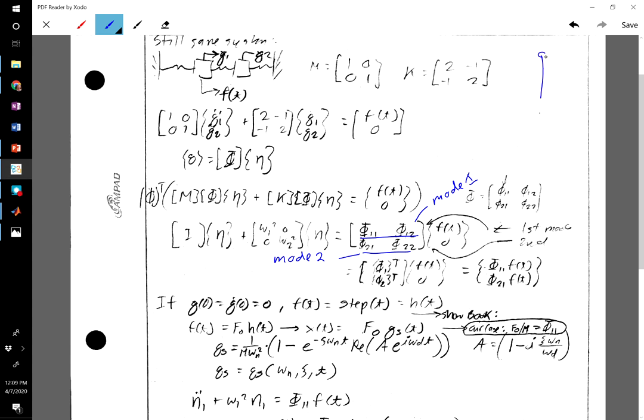Say this was our wind turbine tower, and we've discretized it with 2 degrees of freedom, and we call this one mass 1 and this one mass 2. Not a very good example, because if this was the real wind turbine, we wouldn't have that spring right there. But anyway, the idea is that a gust comes along and applies a force only to one of those masses.